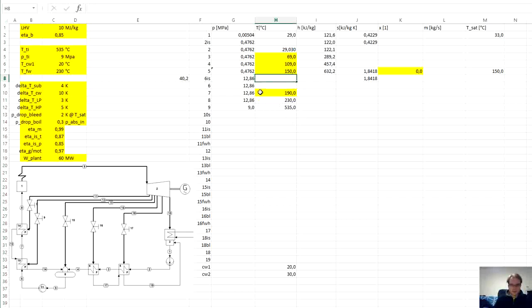So now we get the pressure. We got pressure, enthalpy, it's the calculation of the pump, same as we did before. We can actually use the very same function to get the isentropic enthalpy, and then the very same function to get the actual enthalpy.